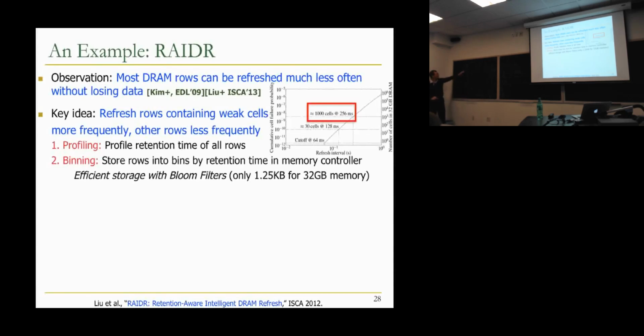The realization is that you don't need to keep this data structure exact. You can reduce it to a much smaller bit vector and allow some collisions. Maybe instead of having 1 million, you have 1,000 bits. And now you know that some rows need to be refreshed every 64 milliseconds, and you know those addresses. Now you need to insert them into this bit vector. This is called a version of a Bloom filter, a poor man's version. It's a very simple one.